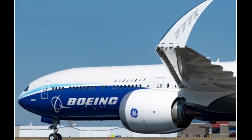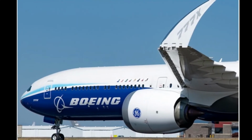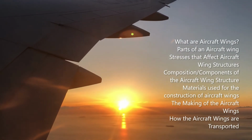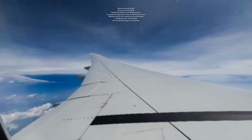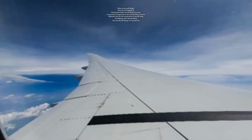The wing structure, or wing frame, comprises three main elements. The skin: this is the outer covering of the wing, on the top and at the bottom. In order to maintain the low weight of the wing whilst still preserving structural integrity, the skin is thin, while there are stiffeners along and across the wing: ribs and spars. The skin is the first part of the wing to experience the stresses of the aerodynamic loads. It then transmits these loads to the ribs.